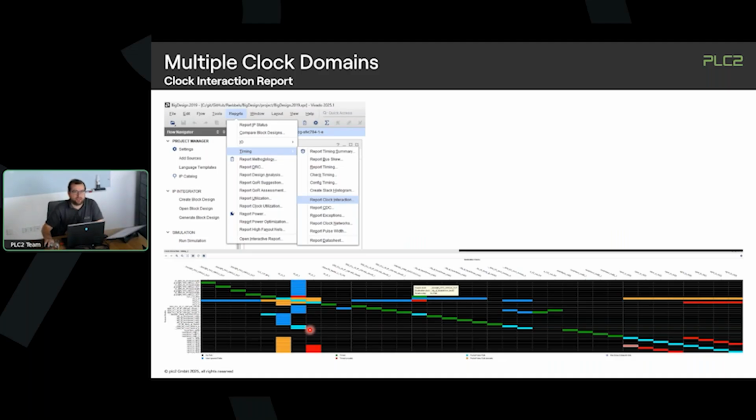They are constrained with data paths or false paths and so on. And then we have certain items in orange and red that are not constrained correctly. So this is what we need to solve. In a good design, you have no orange or red colored entries in here. Otherwise, it's a design fault. So in case you would hire me as a consultant checking your timing constraints, I will look into this. And if I see orange or red, you're failing.